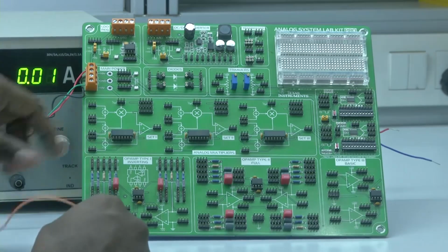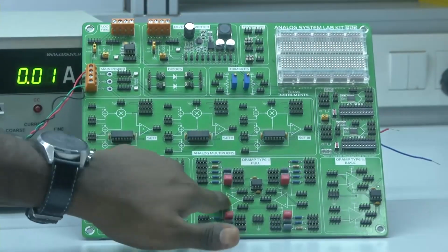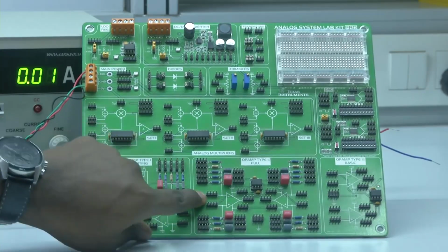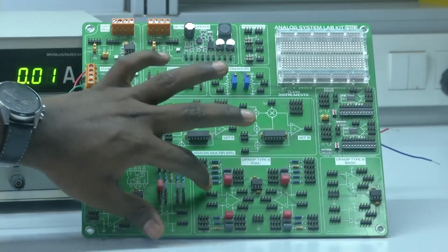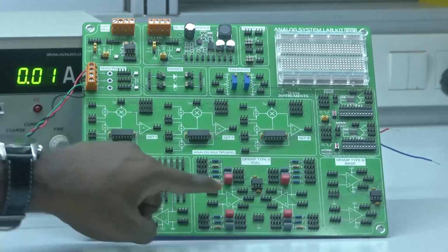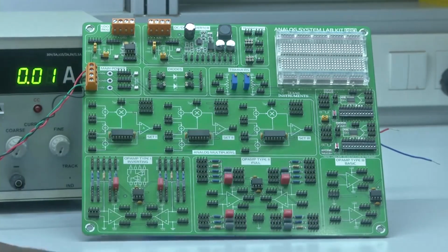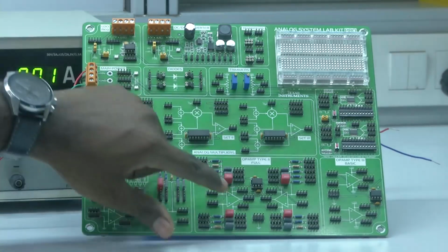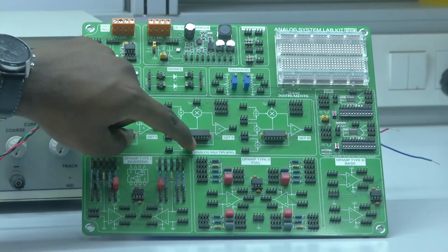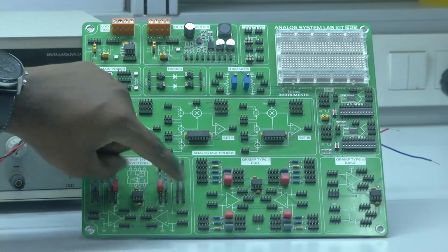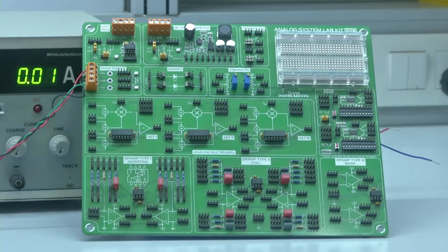If you observe here, the input has to be provided through 1K. If you carefully see the inverting terminal, one end is connected to OPA 2A in. OPA 2A indicates this is the second subsystem of the operational type. A indicates, since it is a dual op-amp, it is divided into A and B. Channel A indicates the first operational amplifier, B indicates the other operational amplifier. To the negative terminal, along with that, it has provided fixed resistances: 1K, 2.2K, 10K, 4.7K and 1K. The other end of the resistance, if you notice, is connected to the banana connectors.